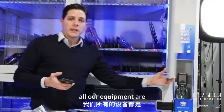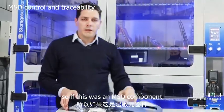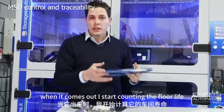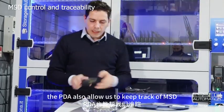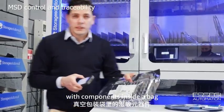All our equipment is equipped with humidity control. So if this was an MSD component, when it comes out, I start counting the floor life. The PDA also allows us to keep track of MSD with the components inside a bag.